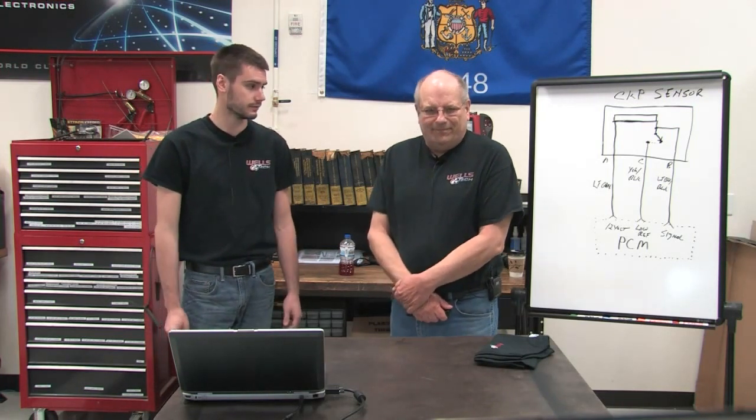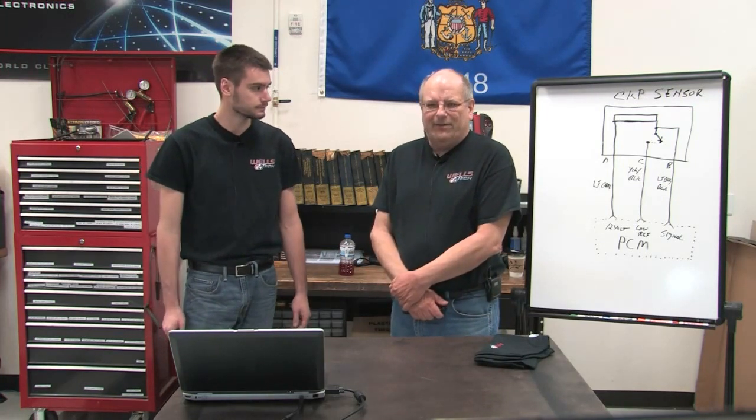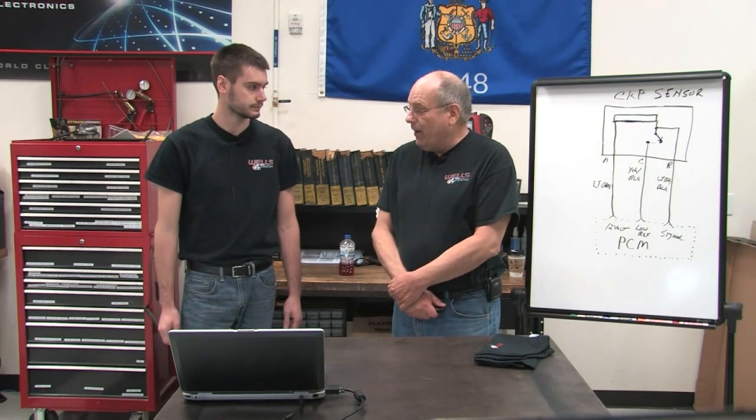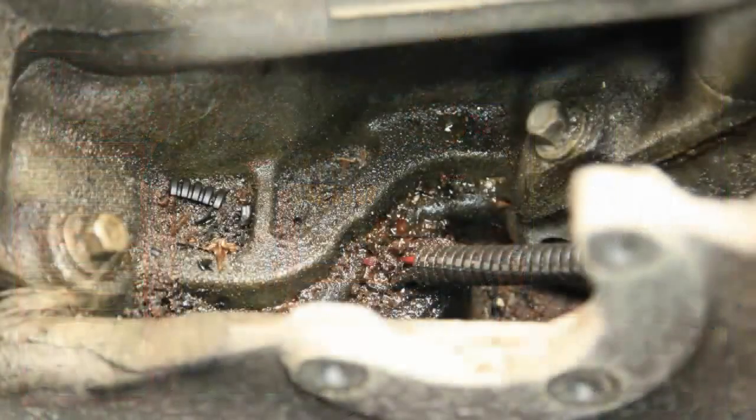Identifix had a ton of confirmed fixes of cam sensors. 95 times out of 100, it's a cam sensor. They have a lot of problems with the wiring going to the cam sensor. Exactly. There's a lot of stress because the wires are bent over the way they are. We'll show that today. Actually, we had that experience ourselves.